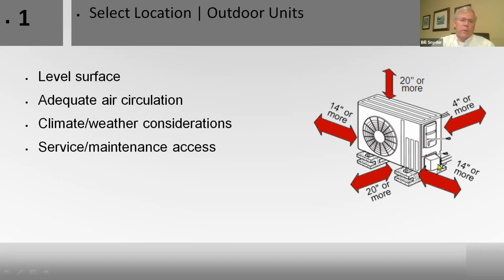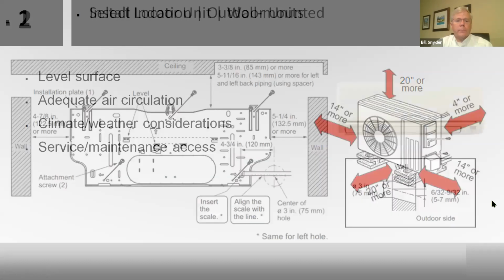You can put these in a very tight area, but again, you've got to be able to work on it. They're showing this up on blocks. This might be fine in Phoenix, Arizona or someplace to put it up on a block like this. Not in our market. That's not high enough, and the water will hit that block and start to freeze, and you'll have problems. So you want to make sure this is on a stand with plenty of room underneath it to drain, and obviously have service access.